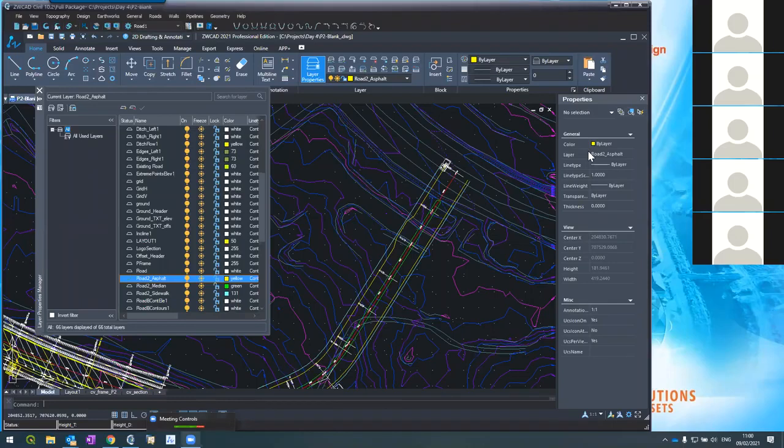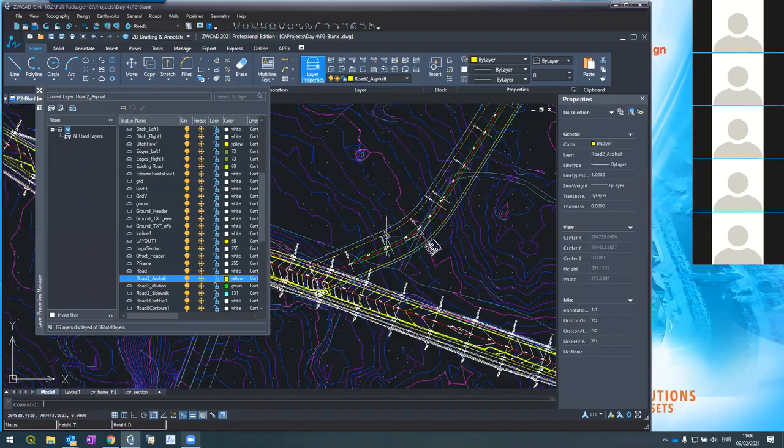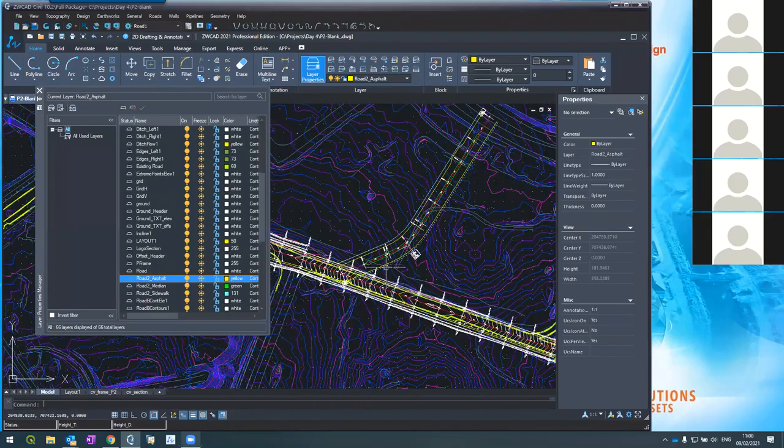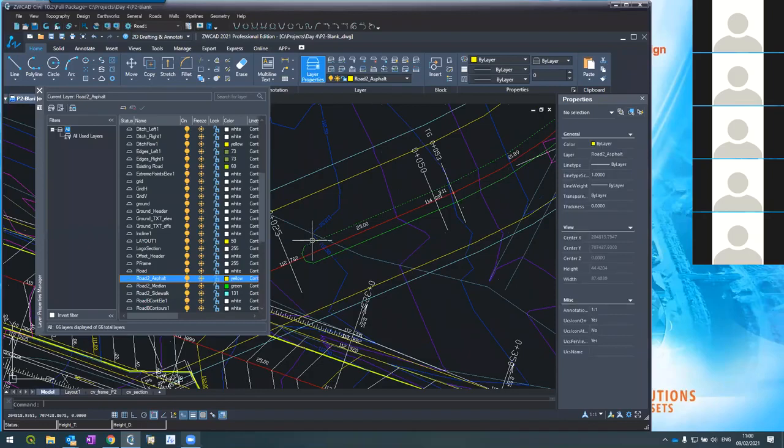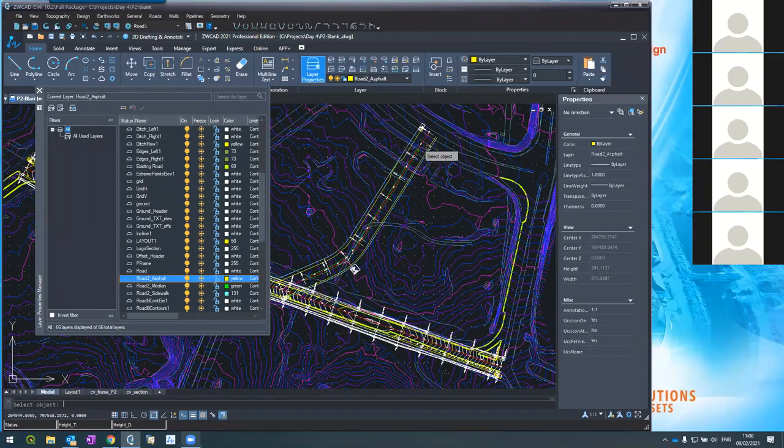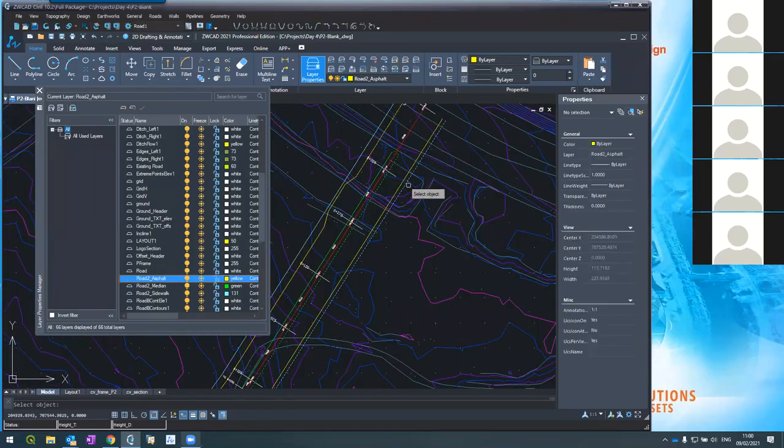I hope you can see. Let me save. Now it's not a must, but to ensure that all goes well, I will join this to be unified polyline. So I'm doing p-edit, joining this, join with this, this, and this.